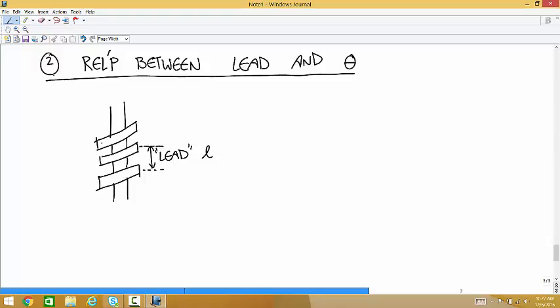Okay. So pitch would be the measurement between each thread. It would be how much higher the ant is the next time he shows up on the same side of the, yeah. But the lead is when you go full revolution? One full revolution, how much higher you are. Oh, how much higher? Yep. The pitch is just the height difference between adjacent threads.